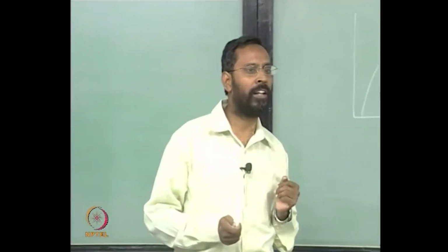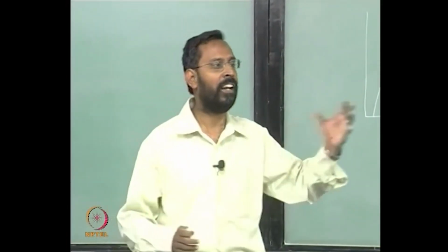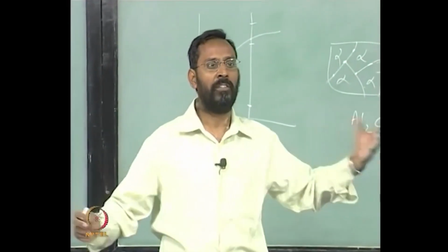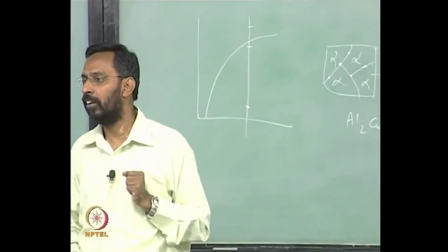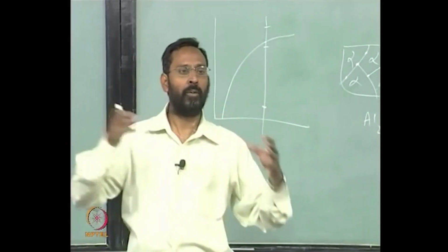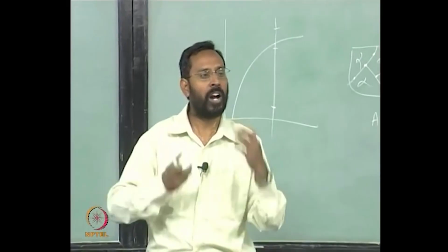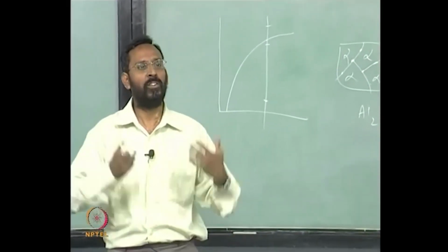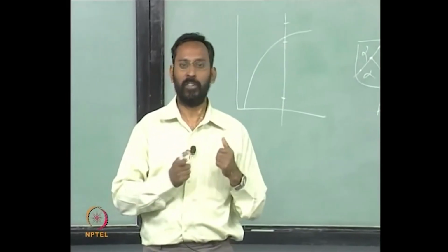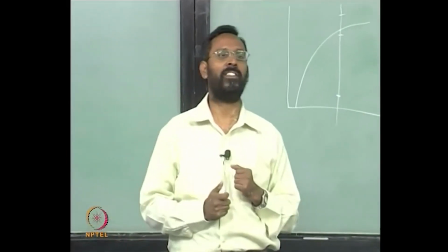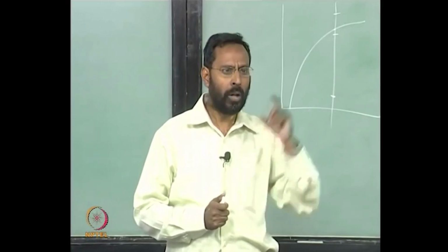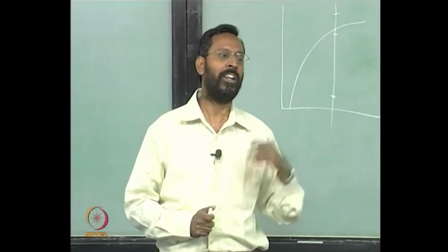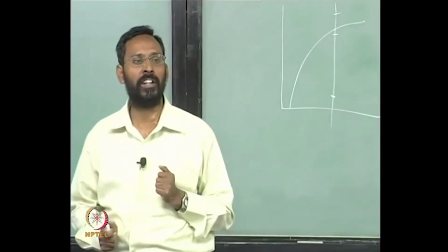Theta cannot nucleate within the grain because theta has a structure which is entirely different from that of the matrix, which is a tetragonal structure, whereas the matrix is an FCC structure. So because theta cannot nucleate, the system starts looking for other things which can be transient phases which can nucleate within the grain. That is how you see the coherent phases come into the picture. Only when the second phase is coherent with the matrix can it nucleate within the grain. If it is not coherent with the matrix, it cannot nucleate within the grain.